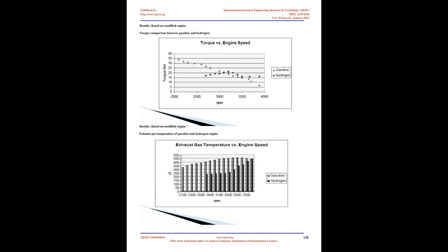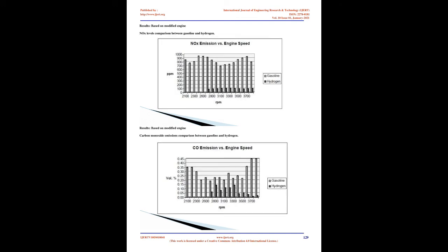Better combustion and expansion of gases take place over 540 degrees of crankshaft rotation, 360 degrees of which is enclosed combustion chamber, and 180 degrees for expansion. The glowing combustion chamber allows the optimal burning of any fuel and eliminates the residues. Better filling of the cylinder on the intake due to the lower temperature of the cylinder walls and the piston head. Elimination of the exhaust gases crossing with fresh air on intake. In the 6-stroke engine, intake takes place on the first stroke and exhaust on the 4th stroke.